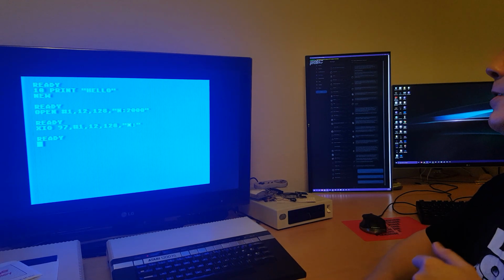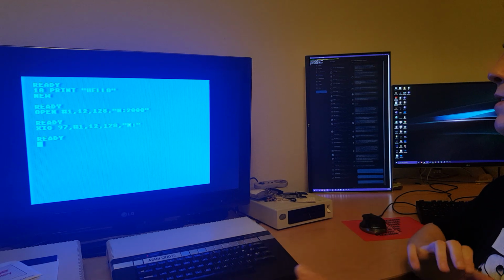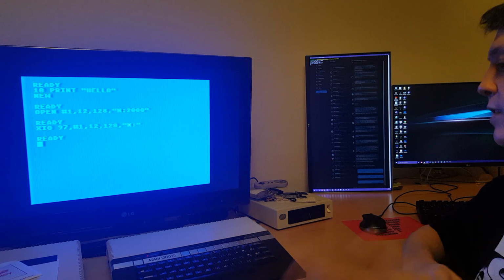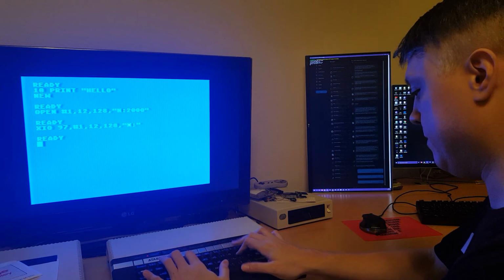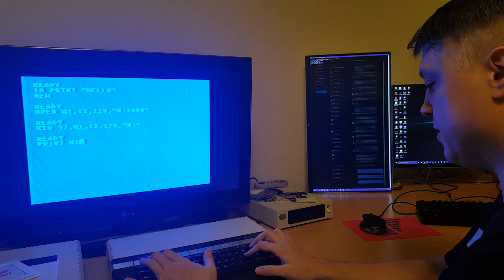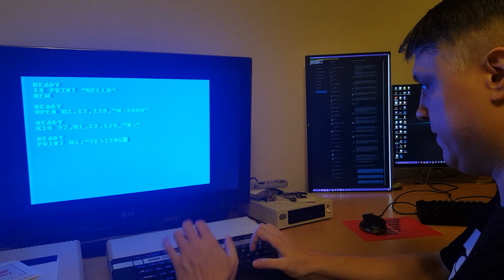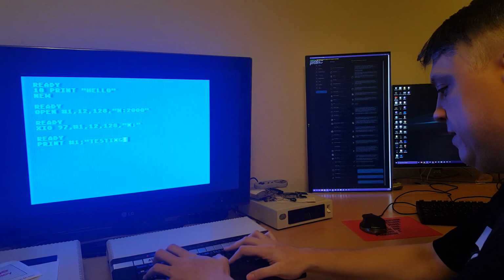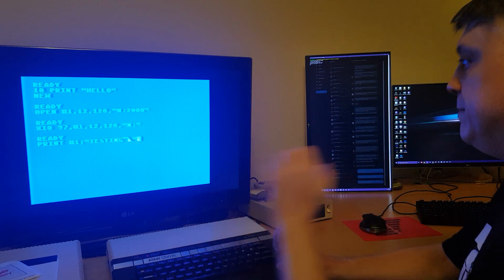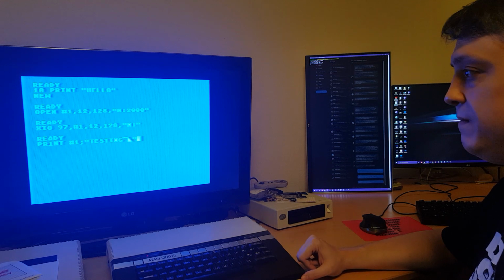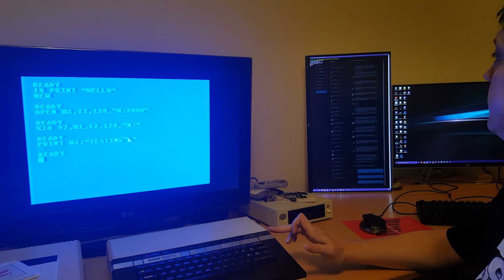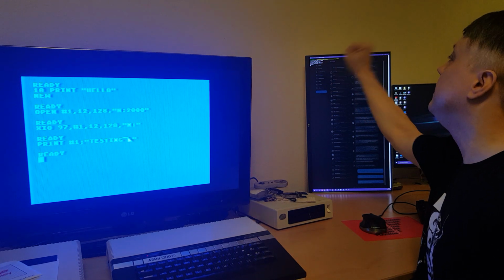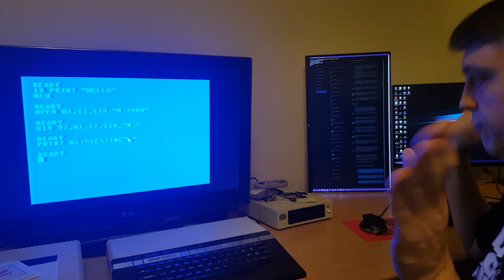And now we can actually read and write to this IOCB as if it were a disk file, as if we were talking to the printer. It really doesn't matter because of Atari's centralized operating system. Now I'm not doing any translation right now, so I'll go ahead and just simulate a carriage return and a line feed here, and we'll send it out the port. And if you actually see, we can see the testing right here. It shows up right here, bam, ready to go.